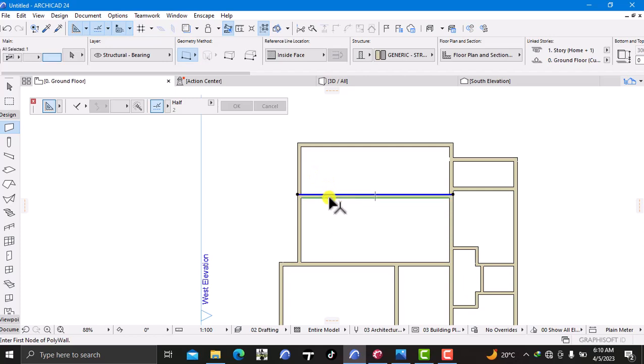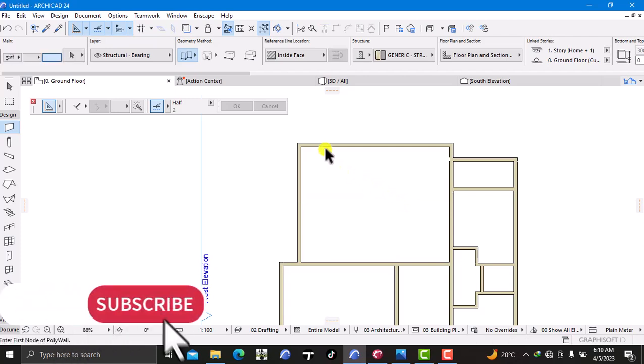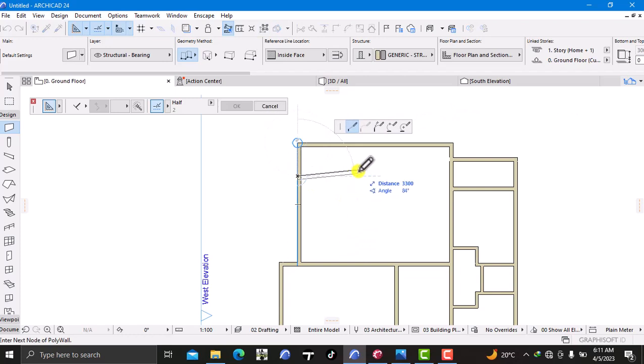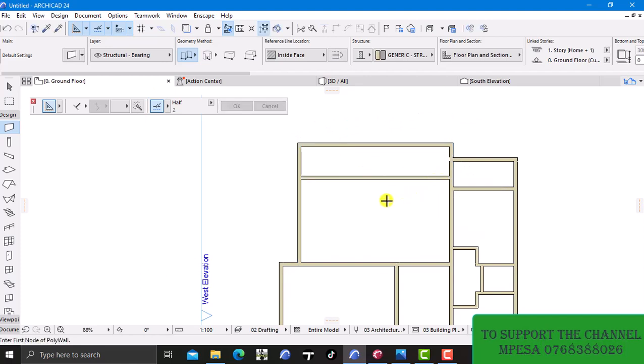So from this point, I'm going to drag, let me first delete this and this also. Let me see. I'm going to reduce this distance from this point. I'll do a distance of 1800. Enter. Basically drag this from this end to that end.